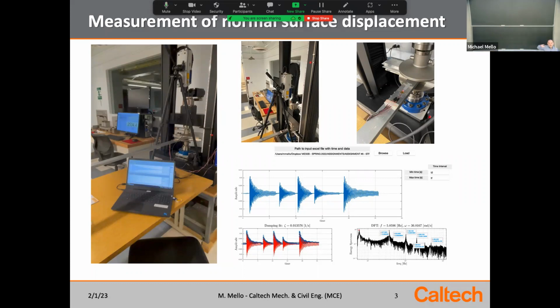And you could simply say, hey, give me the epsilon 1 component, or the 2, or whatever grid strain you want to report. And instead of concerning yourselves with the strain analysis and the Rosette analysis, you could just say, I'm just going to use that strain signal as a metric, and I'm going to extract frequency data from it. So this could have easily been grid 1 on the beam of a Rosette grid. Now, this happens to have come from the vibrometer, but that's the beauty of this, is that there are many, many ways to draw the frequency information from the structure, okay?